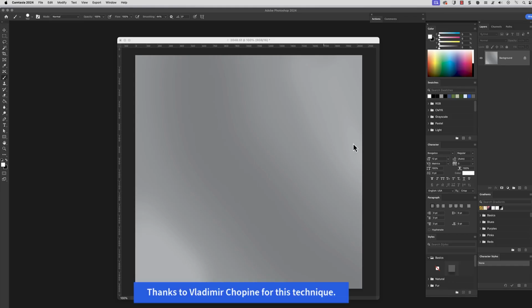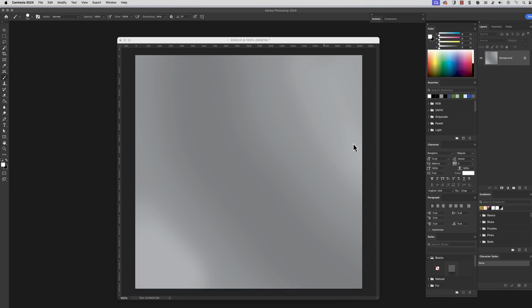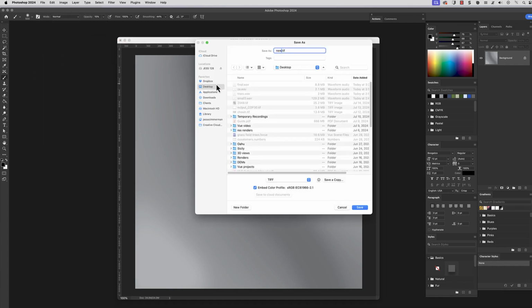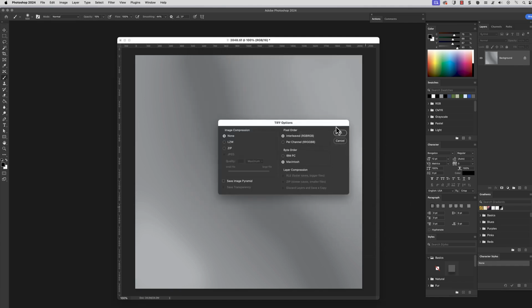We'll start with the terrain we used in the painting method. Open it in Photoshop or GIMP. It should still be a 16-bit file. Get the paintbrush tool and set it to about 500 pixels with 0 hardness, with opacity set at 15%. Select black as the color and paint a line through the scene like this. This will be a river valley. Go to File, Save As, give it a name, and save the file as an uncompressed TIFF.